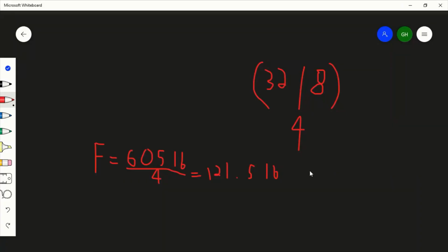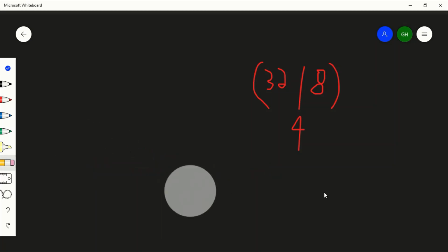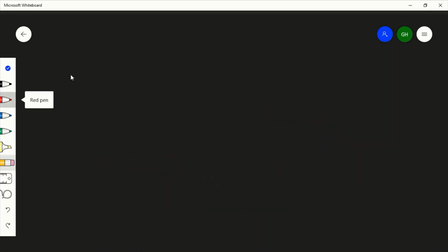All right, so now that you're back, we'll start out with our 8-tooth gear, our pinion. I would then connect it to a 24-tooth gear. So now we have a gear ratio of 24 to 8, or 3 to 1. And that's good. That's what we want.